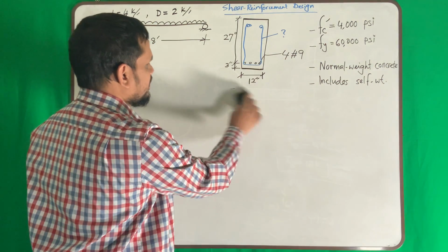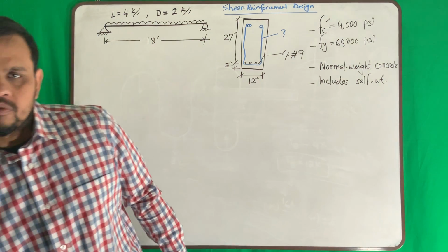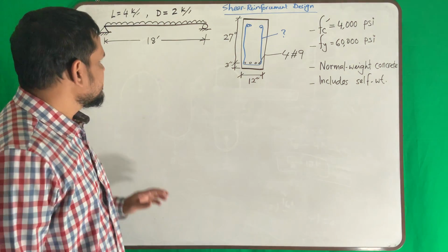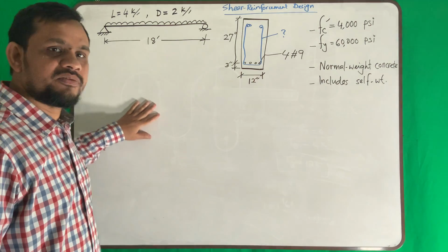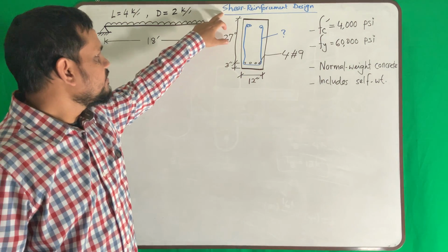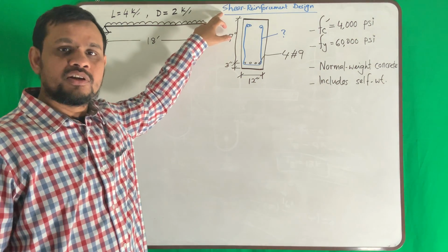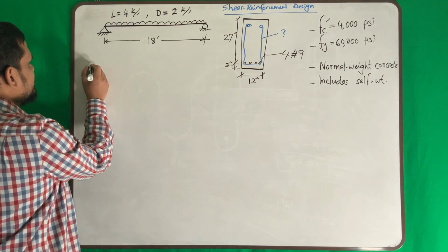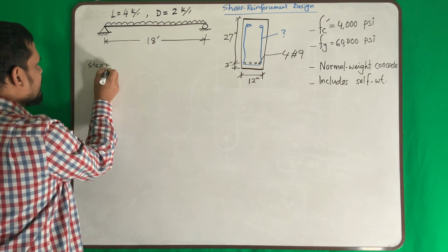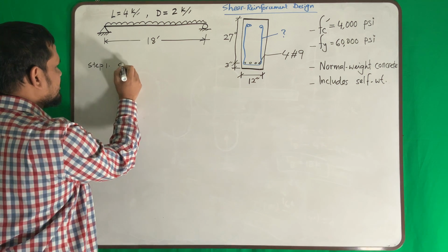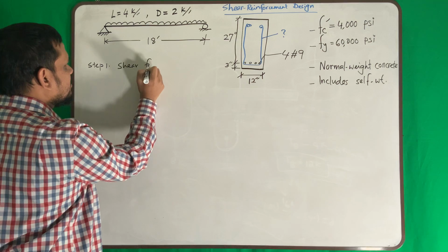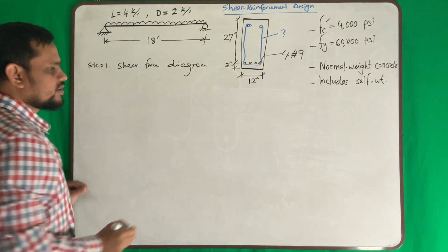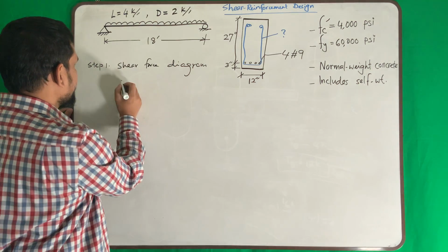Okay. So in my last video, I told you the steps to do it. So what is step number 1? Step number 1, I have to find the shear force diagram. We are designing for shear reinforcement, so we need the shear force first. So to determine shear force, step number 1, I have to calculate the shear force diagram.